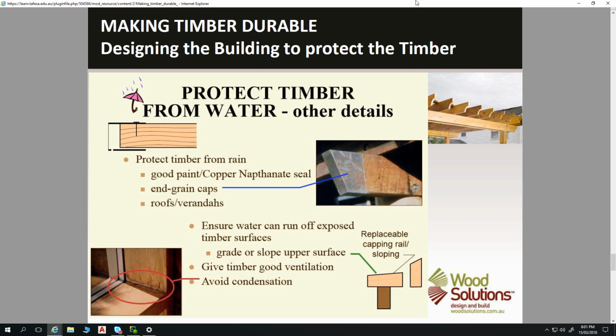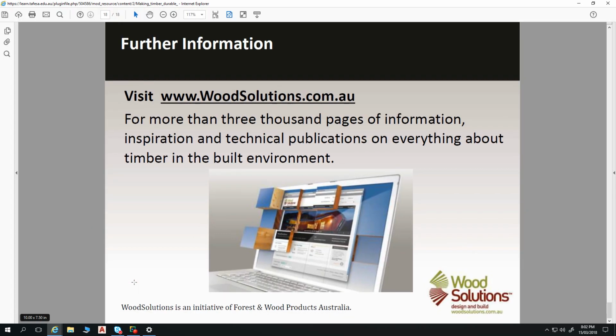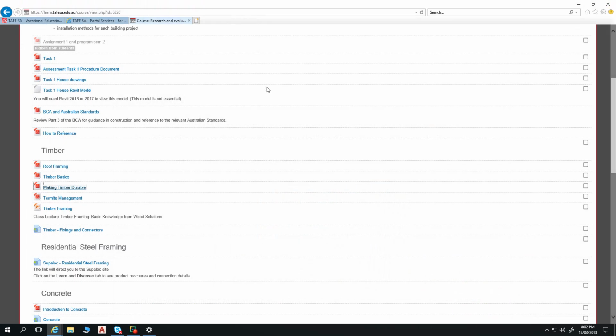If you insulate well, you don't. Where you insulate poorly is where you get condensation. And unfortunately, that happens on windows here as well, because of course you can't insulate the window. You get moisture build up on the inside, as the outside of the window pane is cold, the inside is warm. So that's in regards to durability.